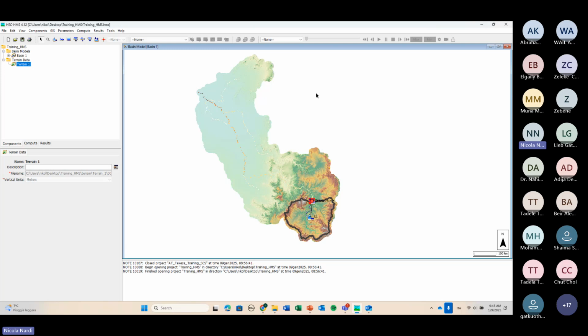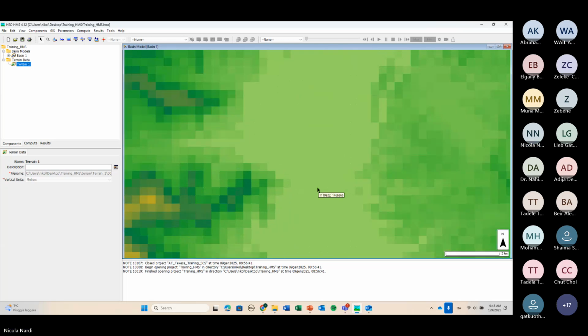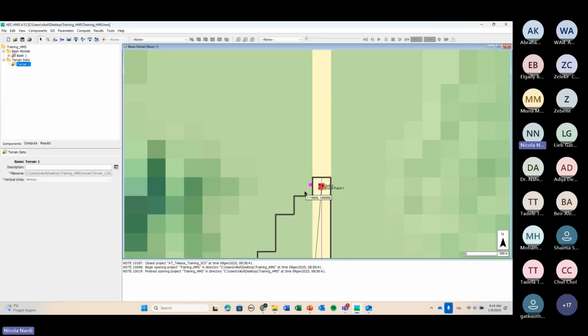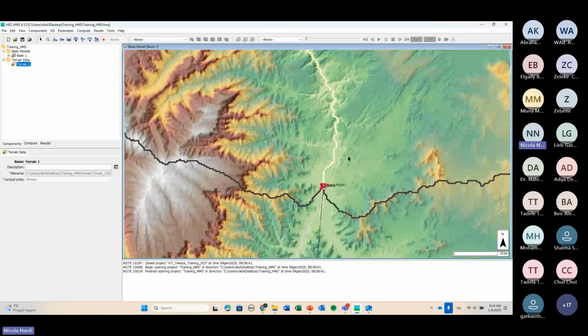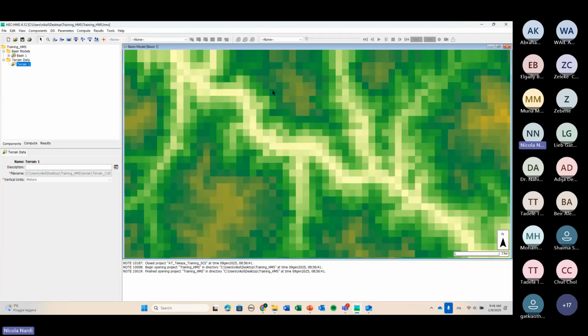The simple one is just to move the breakpoint. For example, I selected this as the location of my breakpoint, and then I see that the layer that I have uploaded as my reference point is the wrong one. Okay. So, for example, I add a new layer for a new reference point, and I see that my breakpoint would have been, I don't know, 100 kilometers upstream. What I can do is really easily just move my breakpoint to a new location.